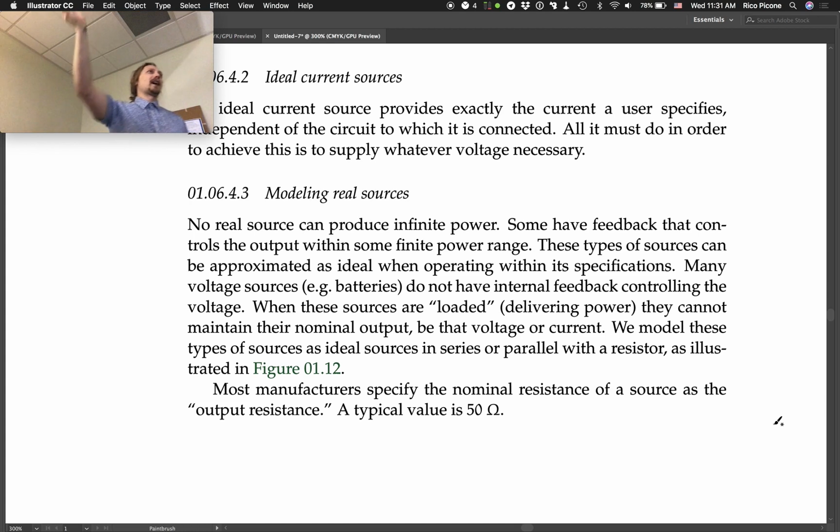So once you ask it for very much power, the voltage that it's providing isn't really the voltage that you're telling it to provide. Also, the benchtop DC power supplies that we've got in the lab are regulated as well, but they have power limitations, much higher power than the myRIO, but at some point it can't provide it anymore.